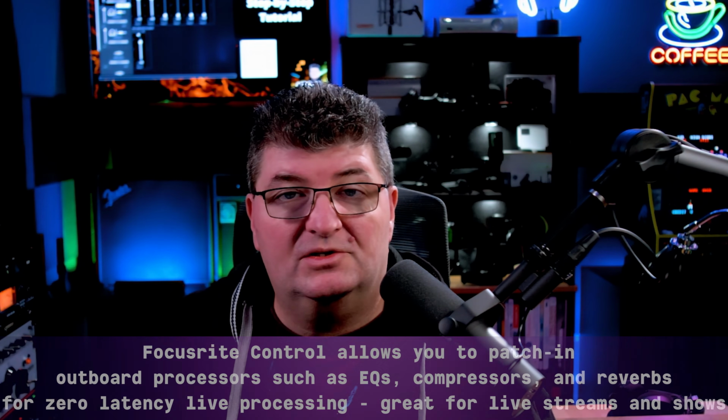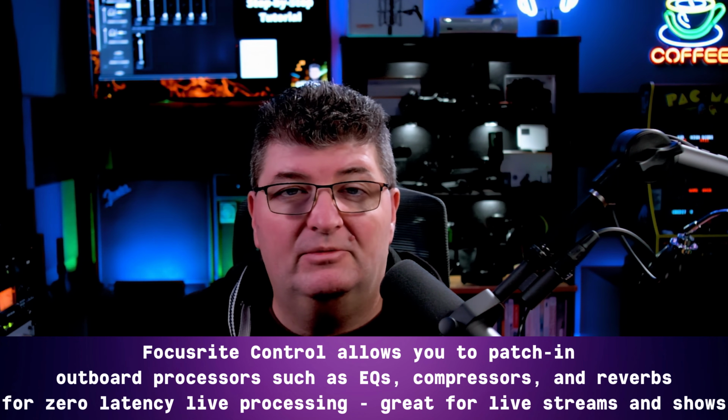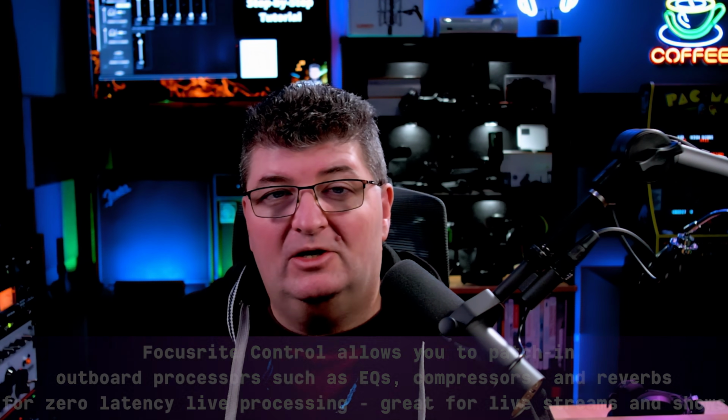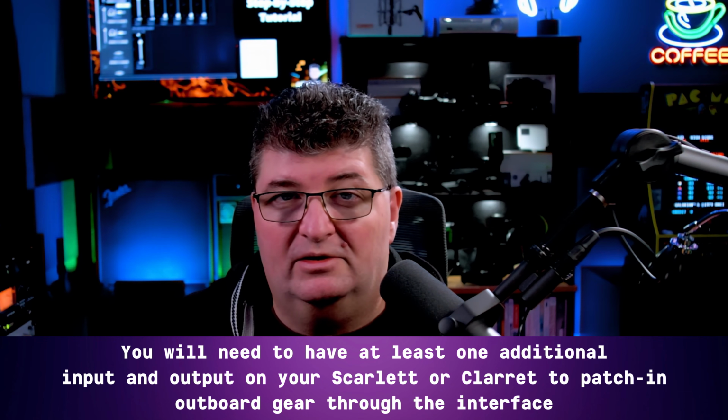Now, you can also use your Scarlett or Clarett interface to patch in outboard gear. And of course, if you're using a DAW, most have the ability to patch outboard gear in just like a plugin. But that may not be the case with all applications. Like Adobe Audition at the time of this recording doesn't support inserting external or outboard gear, or even OBS Studio if you want to use an external processor in line with your microphone. But you want to use the preamp maybe on your Scarlett, but you want to add in a compressor or you want to add in an equalizer. You can do that as long as you have an additional input and output. And so let's drop into Focusrite Control and I'll show you how to set that up.